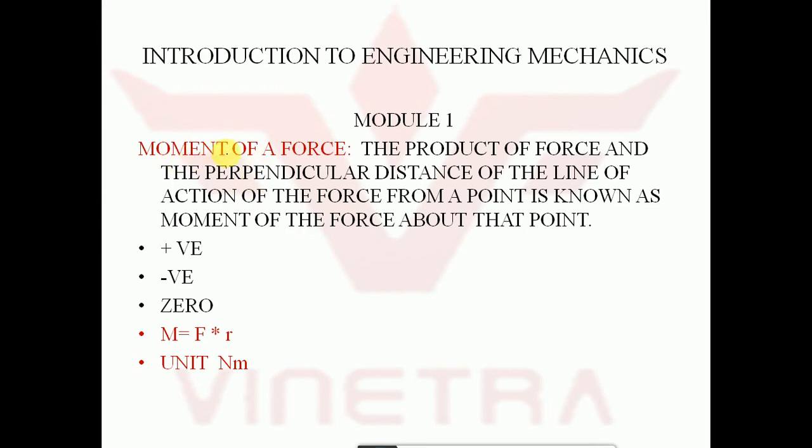So moment of force. The moment of force is defined as a product of force and perpendicular distance of the line of action of the force from a point, and is known as the moment of force. So how are we defining a moment of force? That is, if this is force F, I want to know what is its moment about this given point A. So what I will do, I will extend its line of action.